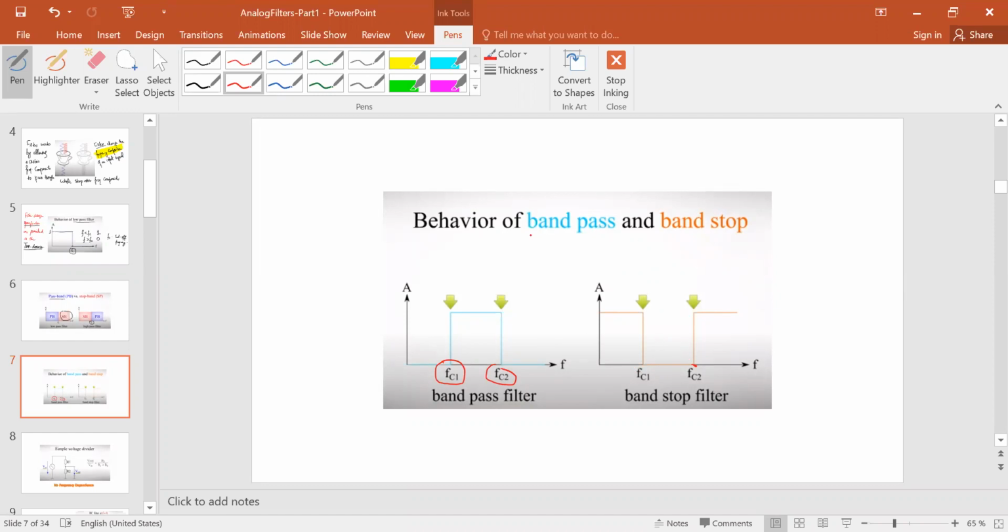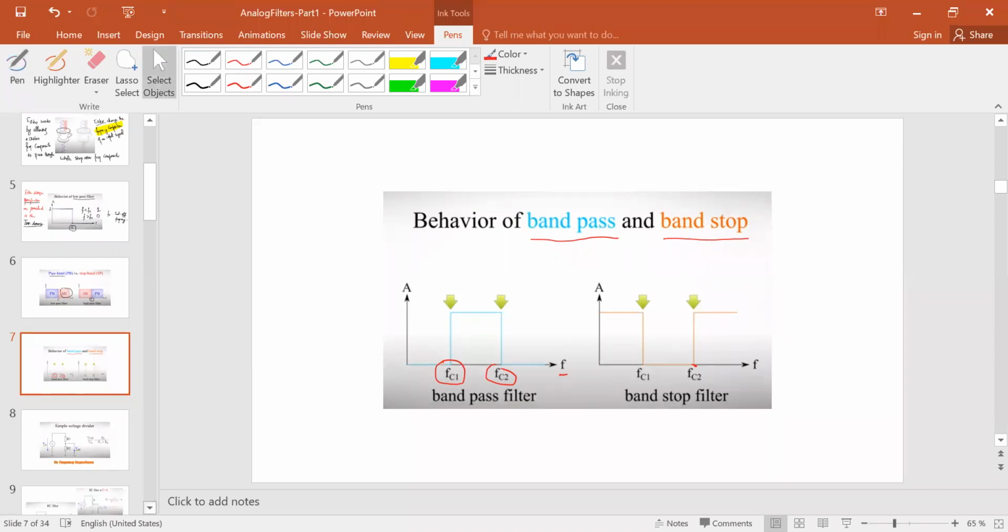So we have band stop, but keep in mind the axis. You see all the specifications are given in the frequency domain. There is no time reference here. So whenever we start designing a filter, we always start from the frequency domain. These are the ideal characteristics that are given to us in the frequency domain, and now we have to design a filter based on those specifications.